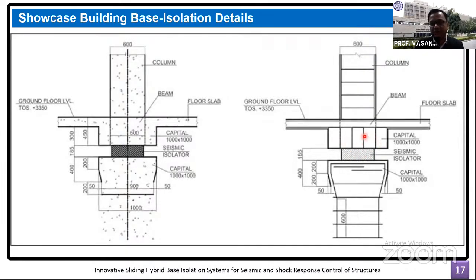Again, you see here a kind of a column capital, both above the column as well as above the isolator. We could have still placed this immediately beneath the beams here. However, again, it was a design decision to put some larger size member at this level. This floor slab, of course, acted as a base raft or the base mass, which is essential for activation of the seismic isolation system.